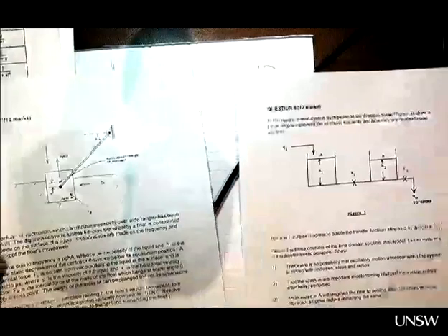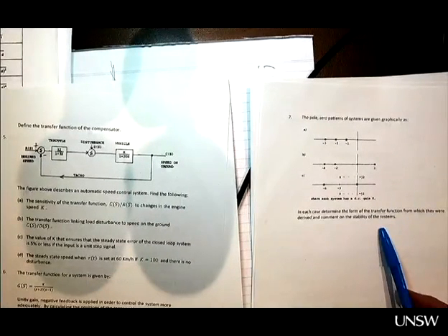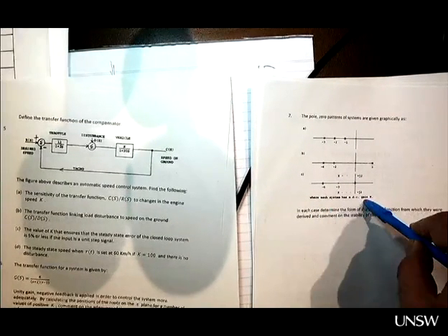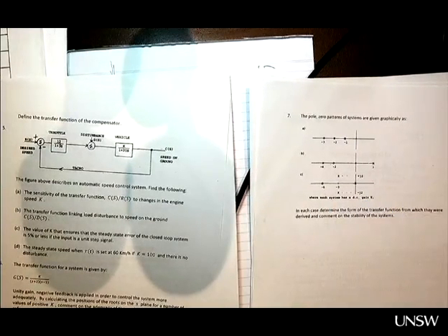In this week's tutorial, this question gives the poles and the transfer function, and it says the DC gain is K. But in the solution it's written in a normalized form. That's not the same DC gain though, is it? You need to divide. Let's see. Yes, you're right. That's K1, but the 1 is invisible.